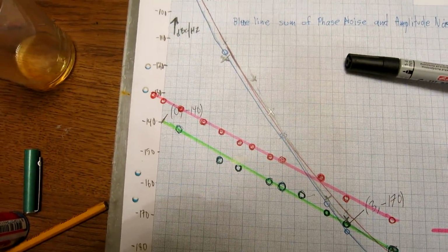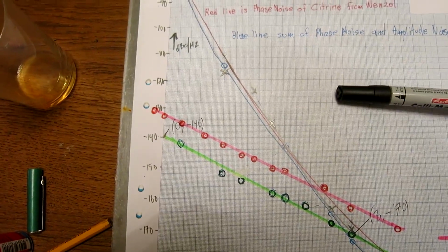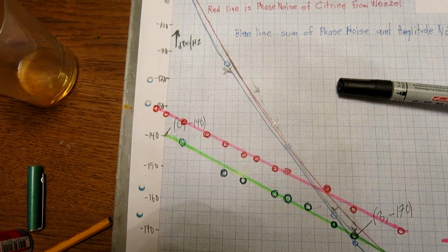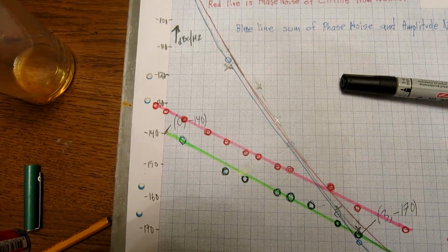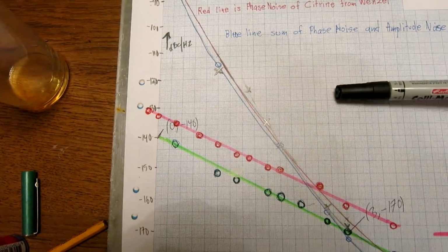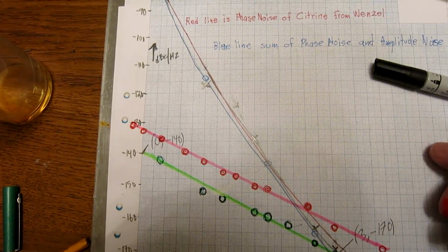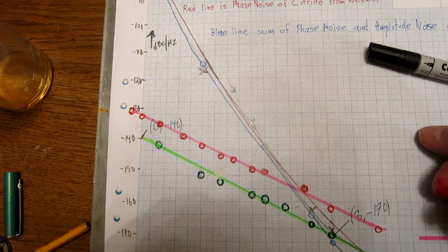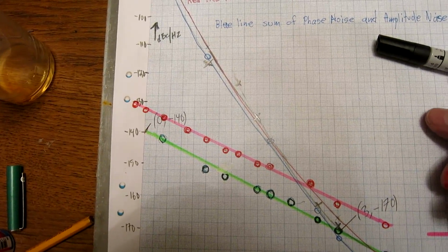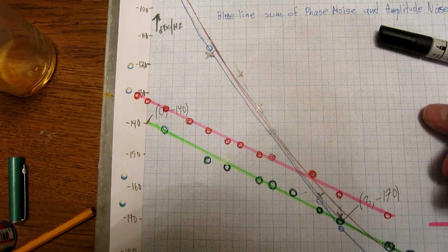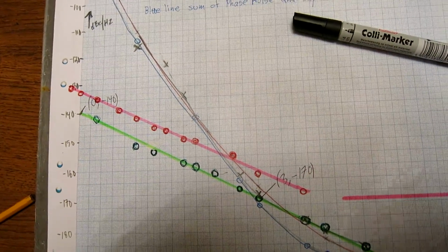And normally, low noise oscillators, they are for having a very good stability for measurement of time. And that happens at even lower frequencies. So this amplifier will not introduce any problem with the Allan variation, which is the same as frequency instability, but it does give modulation at higher frequencies.